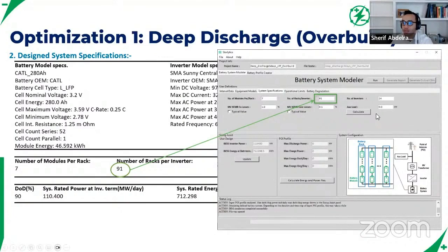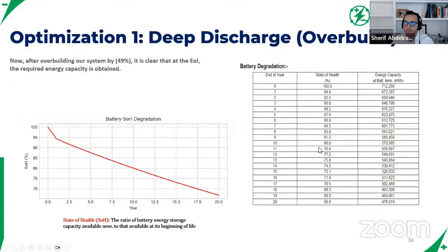I want to say probably 99.5% of auxiliary load is HVAC load for cooling and heating the battery cells. The last 0.5% is just control load. So for this comparison, since we're just comparing two cases, we're leaving HVAC load out of the equation right now and comparing based on everything else. But losses within the system, like copper losses and core losses within transformers, are included here.